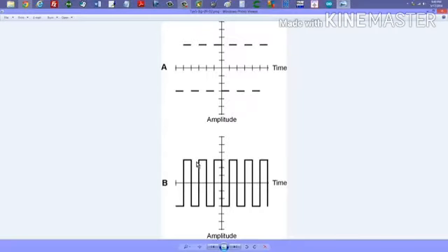And another characteristic of a square wave is that the positive and the negative voltage flat tops here last for equal lengths of time, so that in this case, if we look at 1 second per division horizontally, then that lasts for a second at the positive voltage, that lasts for 1 second at the negative voltage, and the period, the time it takes to complete one cycle, is therefore 2 seconds, one complete iteration of the wave.